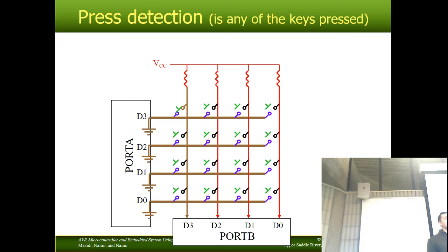So this tells you that at least one button is pressed, but not how many, because you could have all of these pressed all at once. Does everybody see why that's a thing? If you pressed all of these, you wouldn't know. You would still see on your input 7, 0, 1, 1, 1.